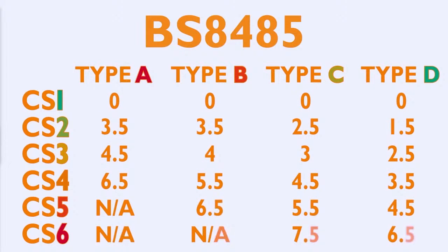At the other end of the scale, Type D buildings such as warehouses have large volumes and poorly sealed or frequently open doors, leading to lower concentration of gas in the internal spaces. Buildings of these types are generally less continuously occupied. This assessment produces a point score for the building and site combination, and this sets the level of gas protection measures that must be applied.